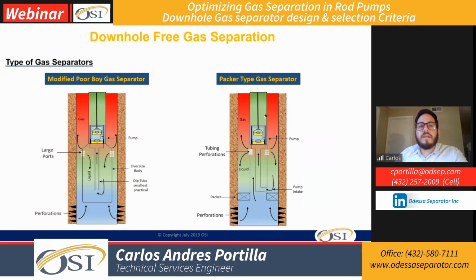And here on the right side, we see a gas separator that is also very popular, which is the packer-type gas separator. For this one, we will need a packer, so we need to isolate the perforations. The industry will be using a mechanical packer, rotational packer, and in some cases cup packers.